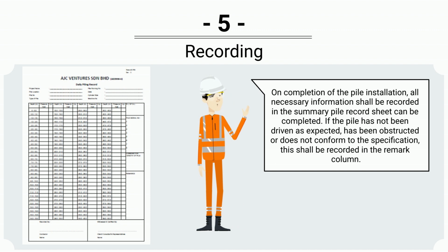On completion of the pile installation, all necessary information shall be recorded and the summary pile record sheet can be completed. If the pile has not been driven as expected, has been obstructed or does not conform to the specification, this shall be recorded in the remark column.